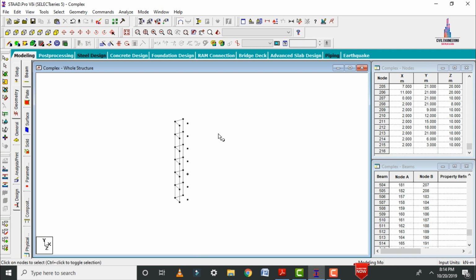So for this respected sections we need to add the shear wall section. So for that select the add surface option here, select the starting point, select the ending point. Again you have to select the starting point, again here to select the ending point like this. So in the same process we have to create the shear walls for the remaining sides for this building.